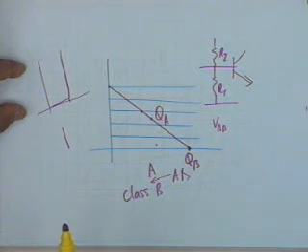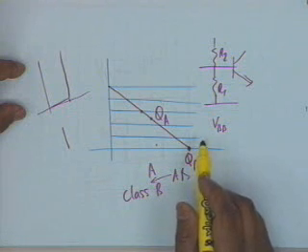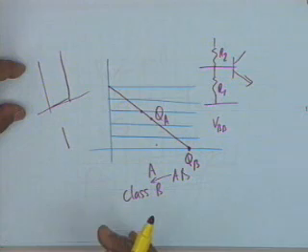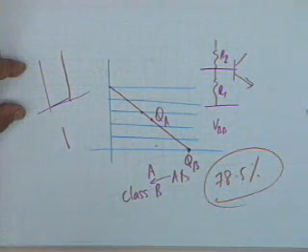0. Isn't that right? Without the signal, collector current doesn't flow at all, and therefore power dissipation in the transistor is minimized. Alright, power dissipation in the transistor is reduced drastically, and therefore the efficiency improves. As we will see, the efficiency can be as much as 78.5%.